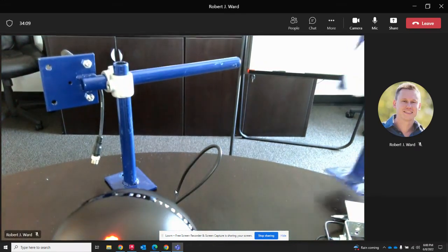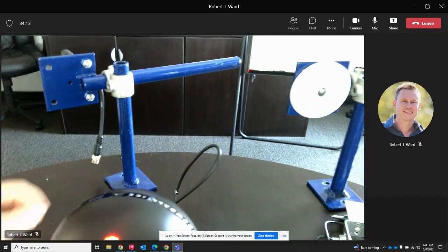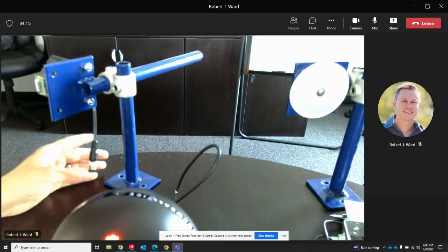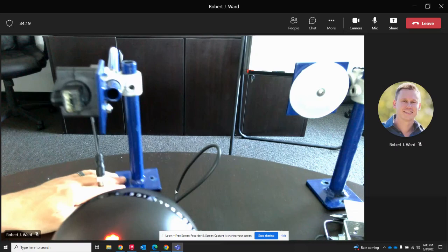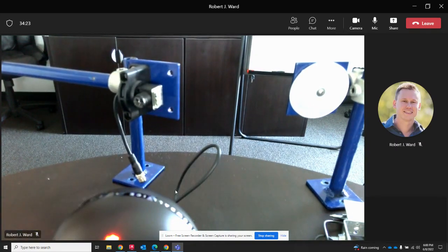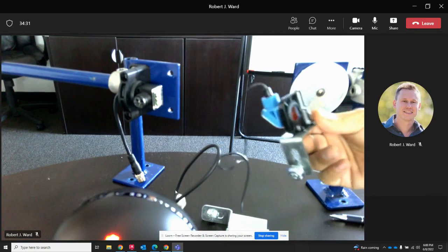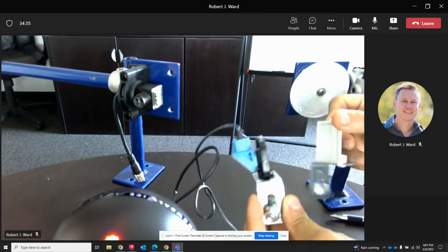So the advantage over this, Michael, you come from an industry that didn't always use these brackets. Why did you guys start using these brackets at your last company? So really, mostly it was just the ability for us to have one part number that worked in, I'd say, 95% of the applications, because typically you're going to end up with a right angle bracket that's at one position on the conveyor coupled with a reflector.